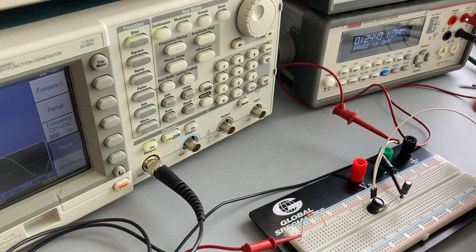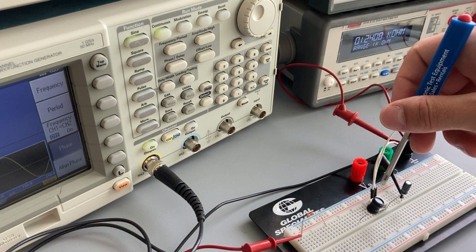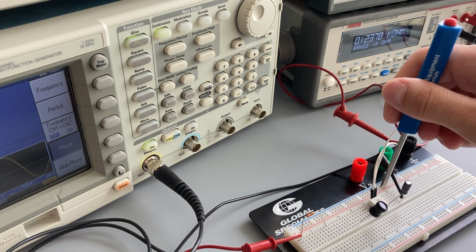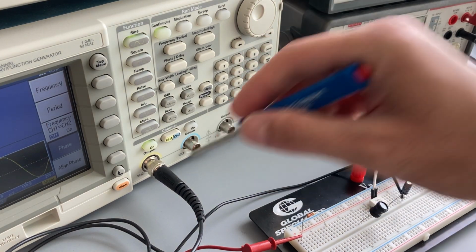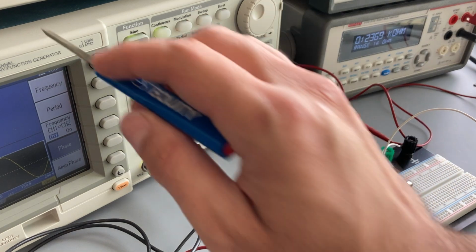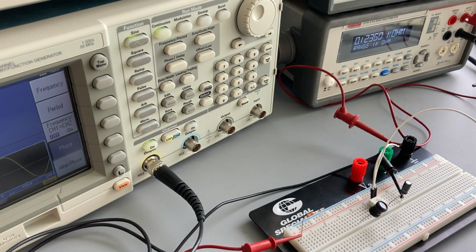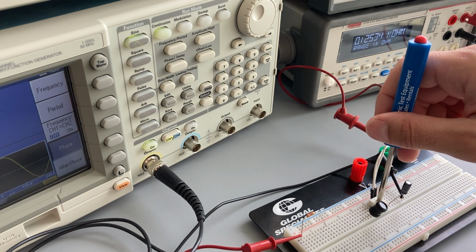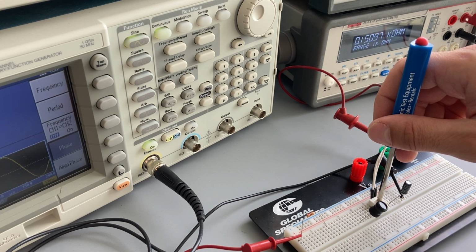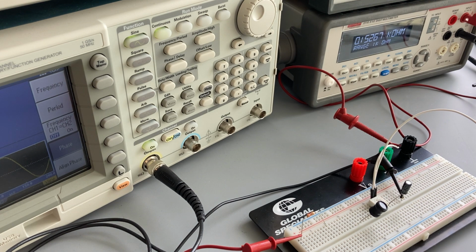I have some value, 124 ohms. I can modify this on my potentiometer by turning the set screw. And I keep my circuit on because since these are separated, the function generator won't affect my resistance measurement. So then I can modify that resistance measurement. Let me increase this up to 152.6 ohms. I'll punch that into my Excel spreadsheet.